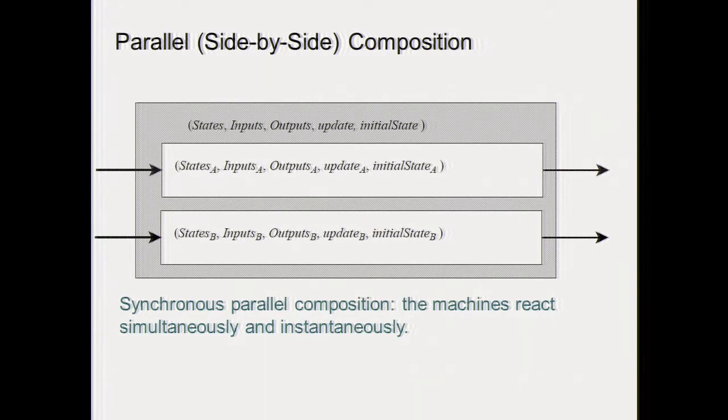So given a particular set of inputs that go to the two machines, you go to a state in machine 1 and a state in machine 2. So it's as if you had a single finite state machine where the states are given by all the pairs of states. And the transition in the composed machine exists if the corresponding transitions in the two machines occur. Okay, that's called parallel composition.